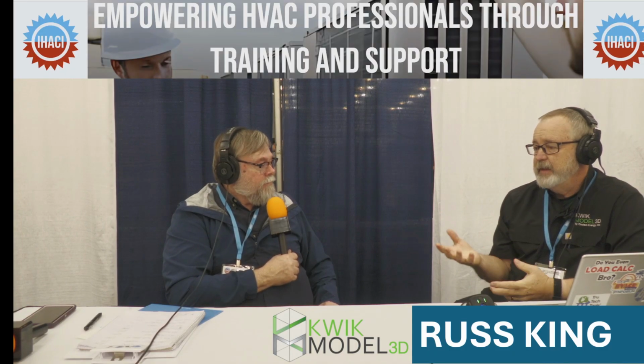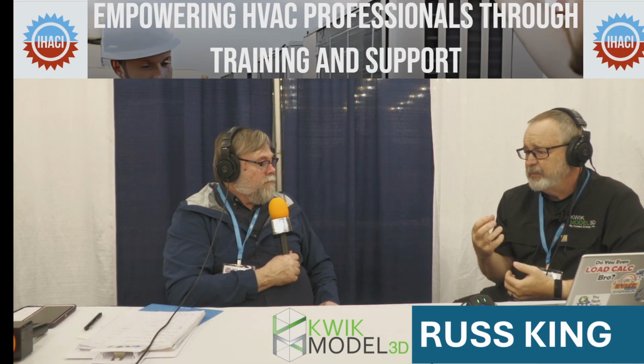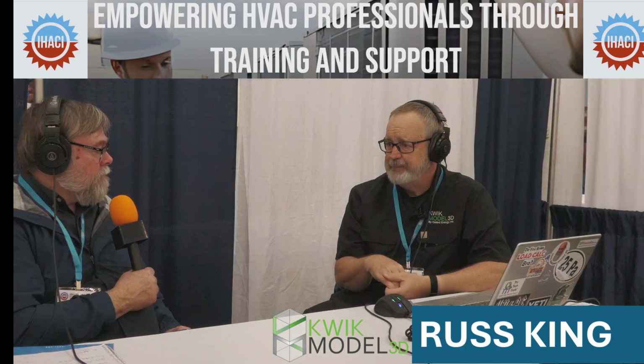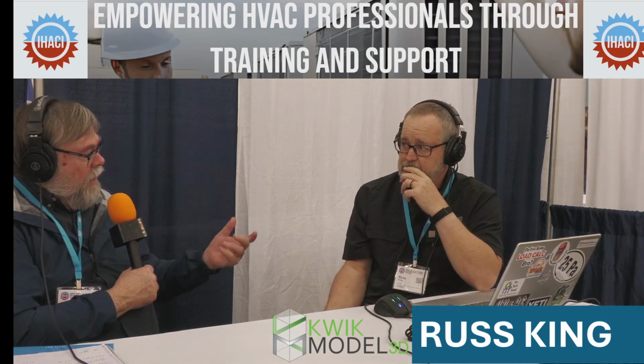And then another big thing is, heat pumps are a big thing now. Heat pumps are really susceptible to bad design. Your heat pump has a fixed amount of heating and a fixed amount of cooling, and they're really encouraging people to size the heat pump to handle the heating load. Who's doing that? The Energy Commission. Is now doing that? Yeah. Really? Because I always thought that we were supposed to size by the cooling load and then put strips on it. And then put strips on it, but you don't need strips in California.